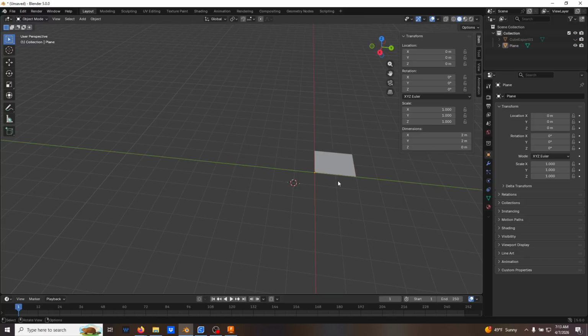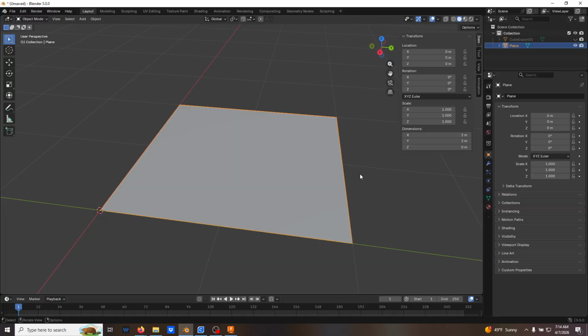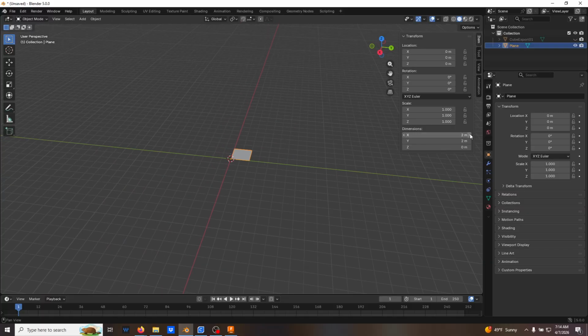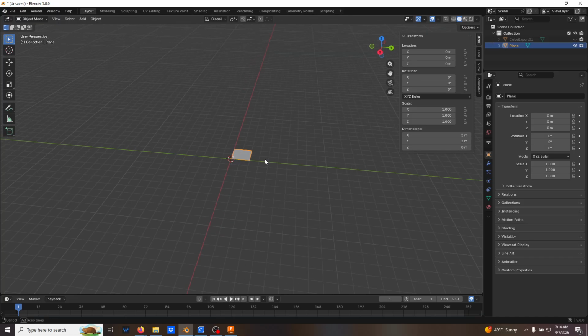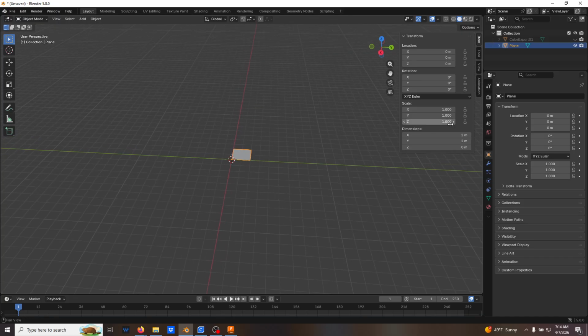All right. So one of the reasons I wanted to move that origin here is because I want to scale this out. I'll Shift C here. I did this before by just selecting the points specifically. This time, since I want this to be 30, I'm going to scale this up to 30 units by 30 units, and then I'm going to extrude it to create the solid object, because you can extrude objects in Blender. This time, rather than messing with it directly in the pop out over here,